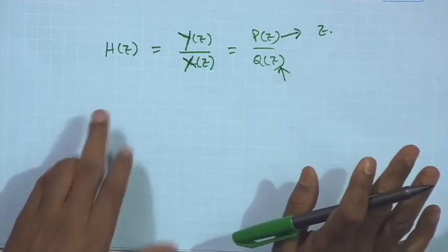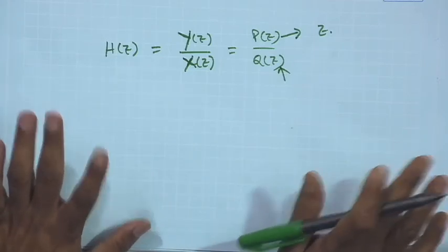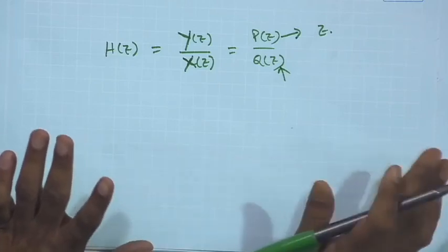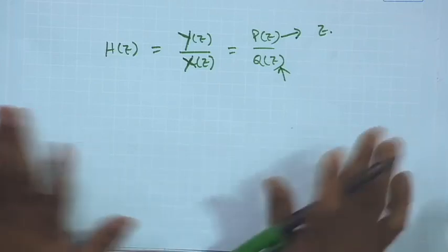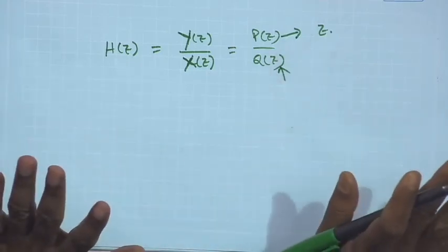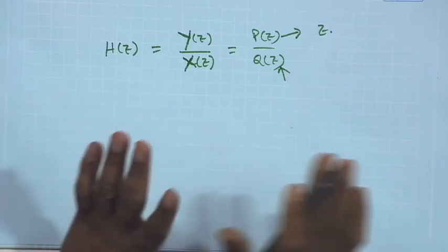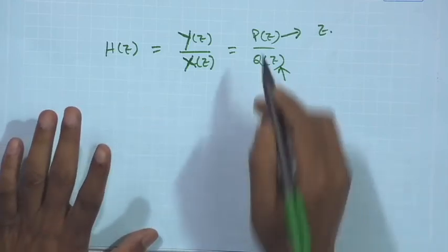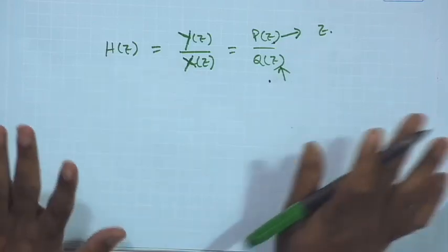That is why H(z) is a pole-zero filter. H(z) has a formant, and the zeros provide the antiformant, or anti-resonance. Okay. So, a pole-zero filter. Any filter can be implemented using a pole-zero function. So, I can implement P(z), I can implement Q(z), and I can implement H(z).